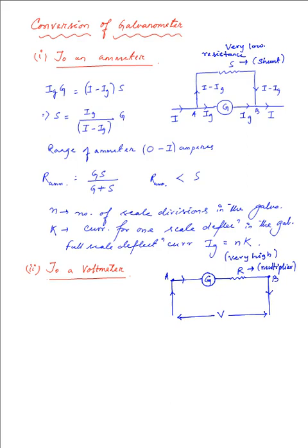This voltage is provided across the combination of resistances, which carries a current, say I. So I times the total resistance, in this series combination the sum of both those resistances, and finally we end up with R equal to V divided by I. Because this current goes through the galvanometer, we can write it as Ig instead of I. So R equals V divided by Ig minus G gives us the value for the resistance.